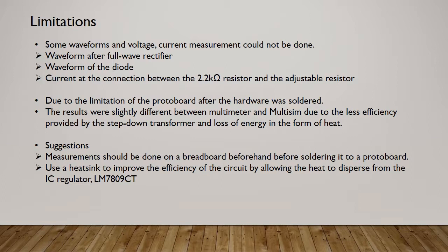And we have some limitations in our hardware measurement. We found that we cannot measure some waveforms and voltage and current measurements directly on our hardware, which is already soldered on the protoboard. These are the waveform after the full wave rectifier, the waveform of the diode, and also the current at the connection between the 2.2k ohm resistor and the adjustable resistor.